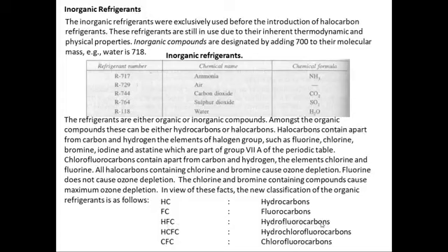So in case of HFC, the ozone depletion potential is almost zero, but the fluorine is a greenhouse gas, so its global warming potential is higher. It's much higher than carbon dioxide. So this HFC is our famous refrigerant, R134a, which is also an HFC. Now there is an effort to find an alternative to that, which are turning out to be the hydrocarbons, and one more refrigerant that is under investigation to replace it.